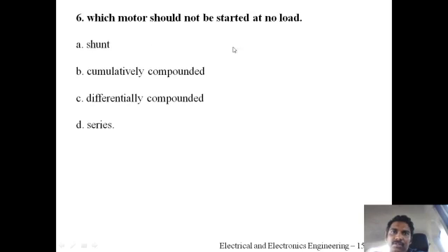Which motor should not be started at no load? Here also, it is the DC series motor we can go for. A DC series motor should never be started at no load. Some load has to be applied, because we have seen from the speed-current characteristics that it will run at a very high speed, which will damage the motor, which will come out of the foundation. Therefore, it should be started with some load. Therefore, for this particular question, you can go for option D.